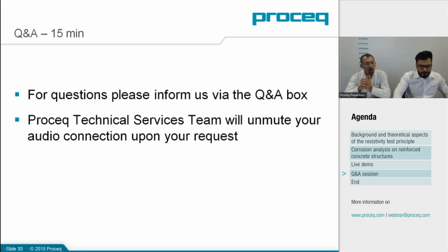So our instrument uses 40 Hertz alternating current. We impose a current which, depending on the two ranges available, is 200 microamperes or 50 microamperes. Those are the parameters fixed on the instrument.